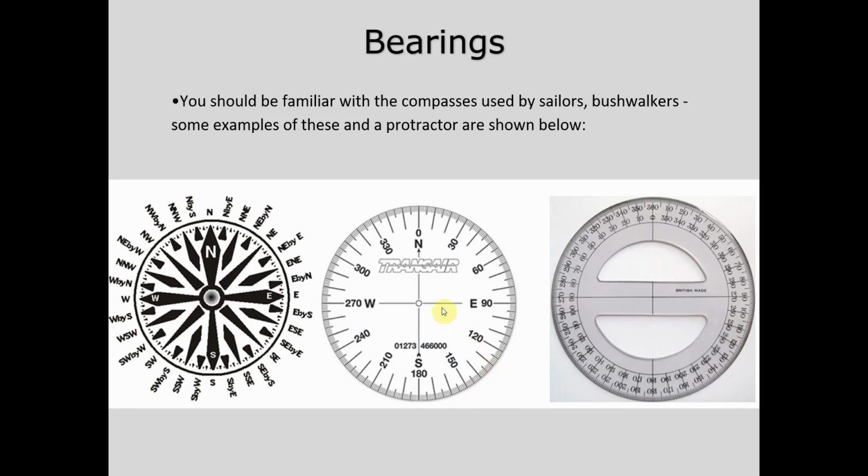Let's set some foundation. The main concept, our north, is always facing up in most cases unless we show otherwise. If the north direction or orientation is not shown, that means north is facing up. So let's use our north. Agree, this is our starting point for measuring any angle. Second rule, the measurement will be clockwise. There's no measurement the other way around. We don't go counterclockwise, the opposite direction of clockwise.